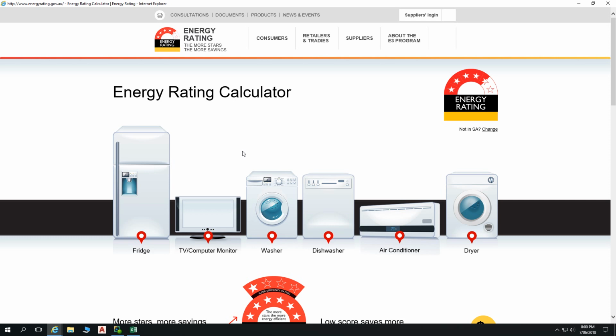Yeah, that's fairly 151 lights. Cool. So you put your 151 in there, and then make sure you write all this down. Or you've written it down, you've calculated it, and you've recorded it. So you've got your 151, and then multiply that by the wattage, or put your wattage into your table, and it will tell you how many kilowatt hours.